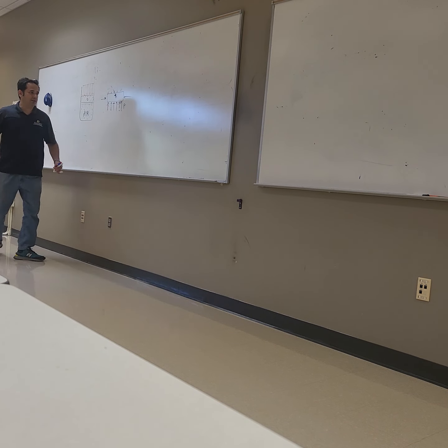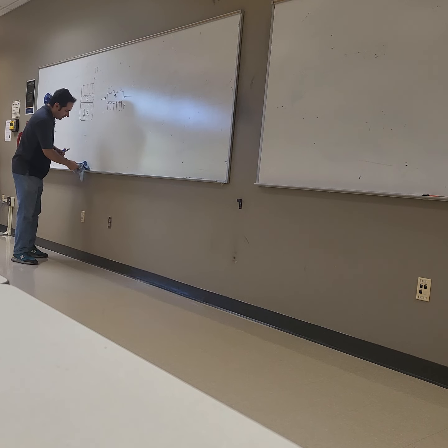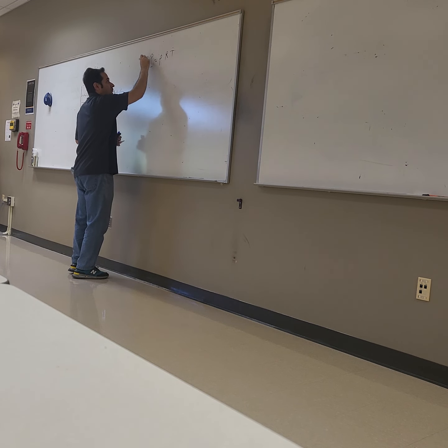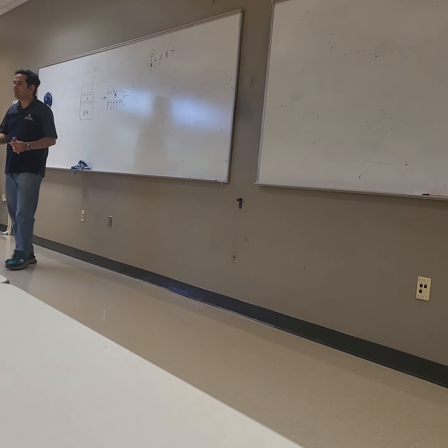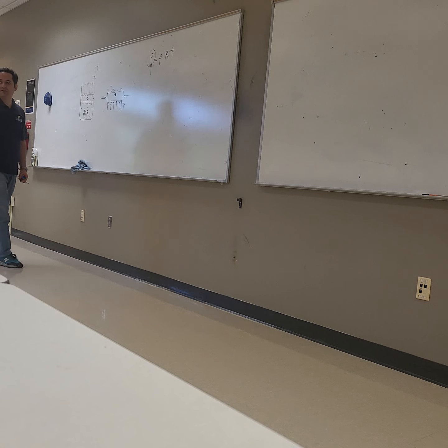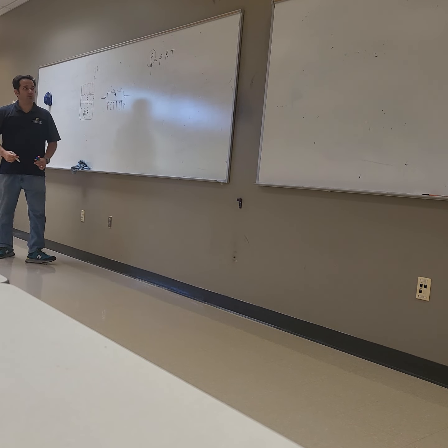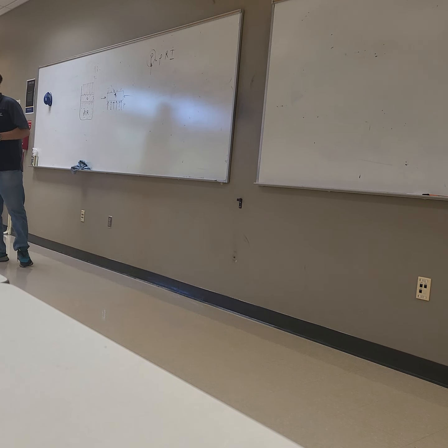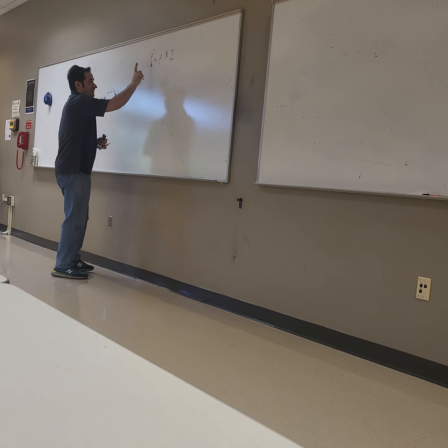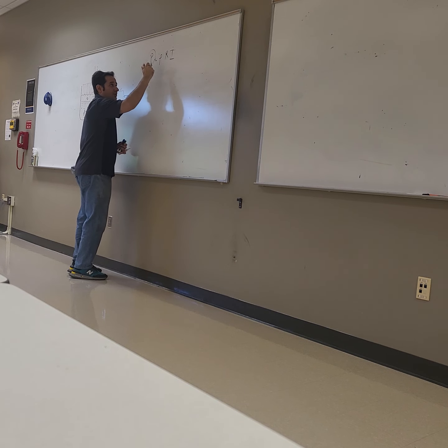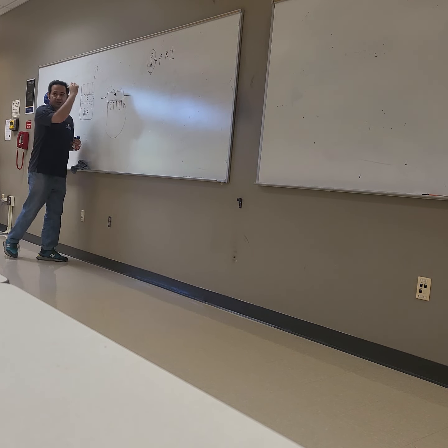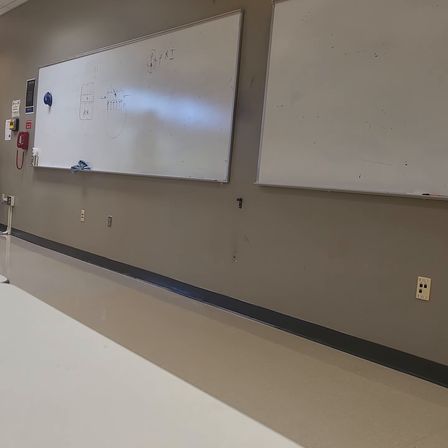But look, if I get my P and I want to get the state of this gas, I go to the equation of state, and the equation of state says P is equal to rho RT. What kind of P should I put there? Absolute pressure. That means the sum of all the pressures. And the temperature is absolute too, Kelvin. It's not Fahrenheit, it's not relative to anything, it's just absolute temperature. So when I use absolute pressure, I have to add this P0 to the gauge pressure to get the total pressure. That's the reason I have to do that.